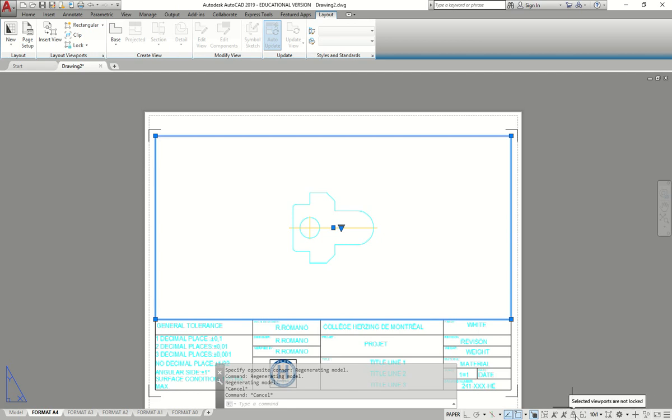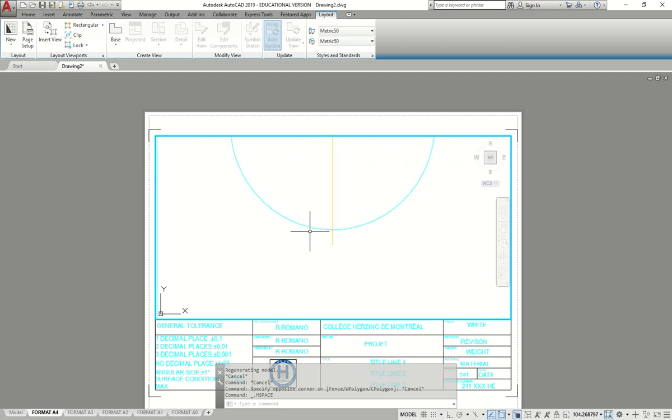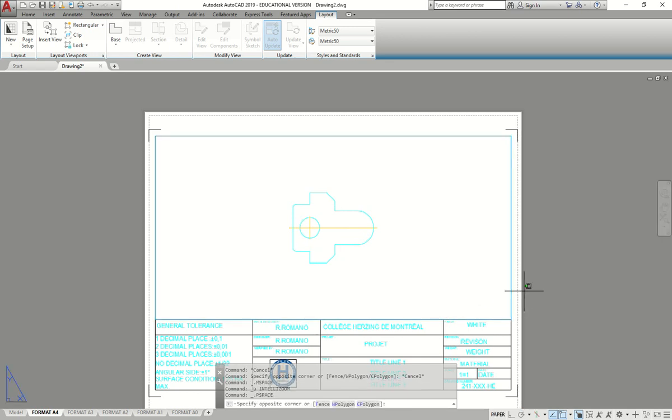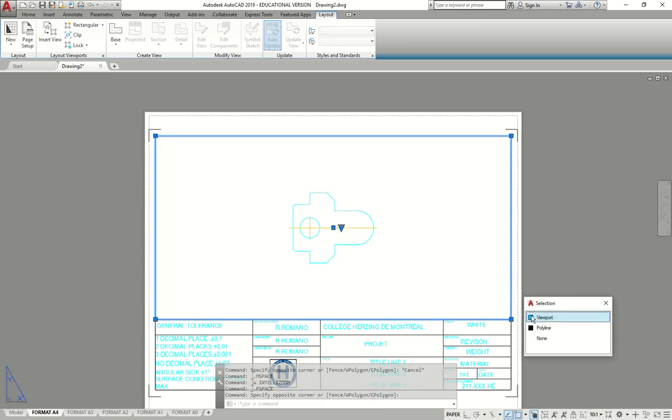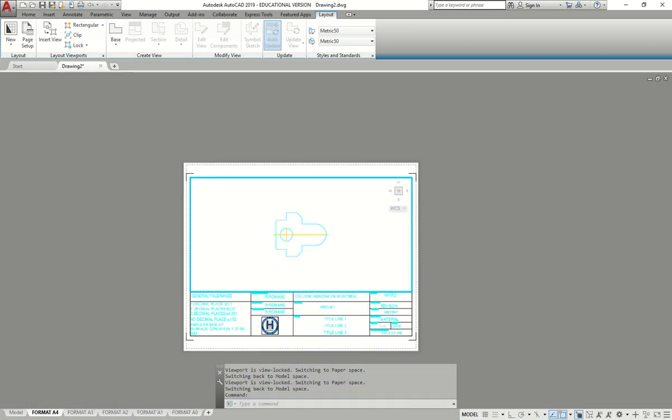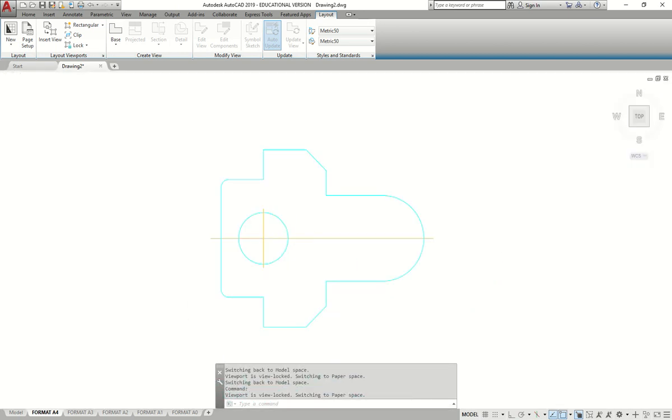the button. What does the lock button do? It's going to make sure that if I click inside the viewport and I move my mouse, it doesn't move the actual drawing. So we're going to undo. What we're going to do now is you double click out, click on the viewport again, command. So even if I click, the view is always going to stay the same.